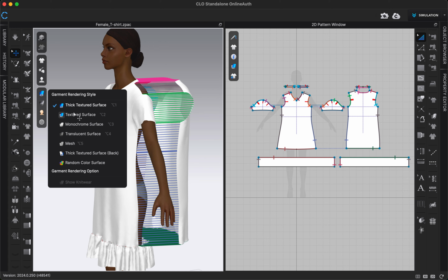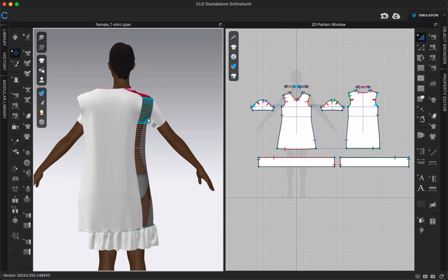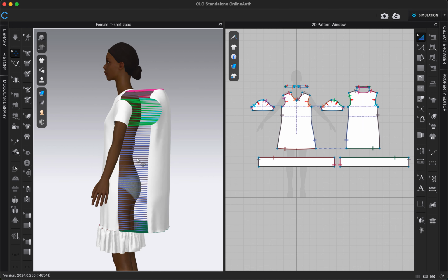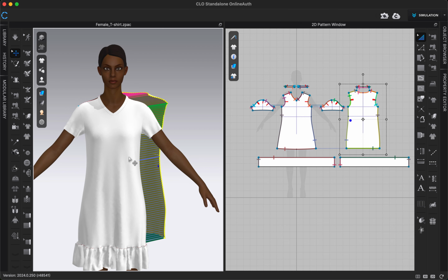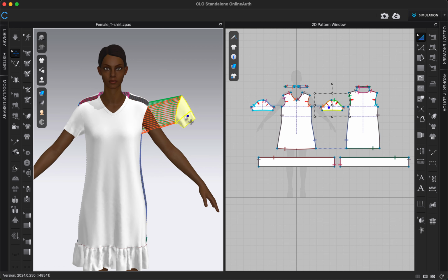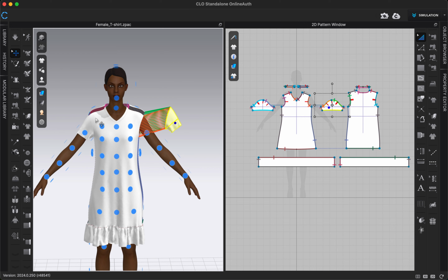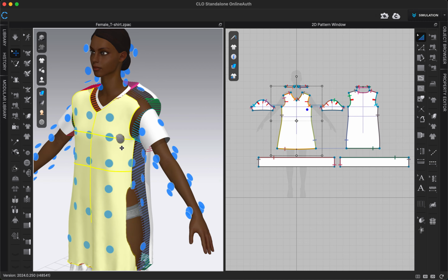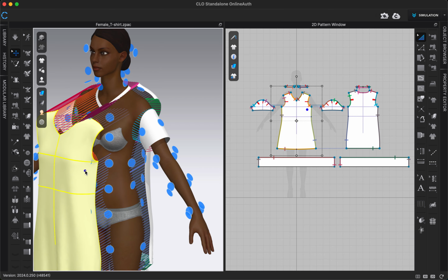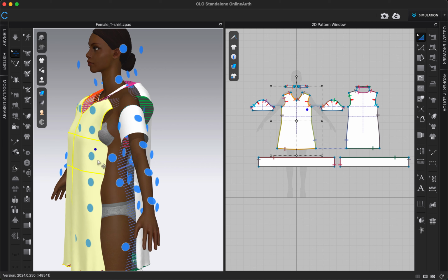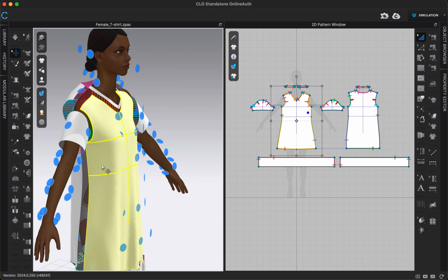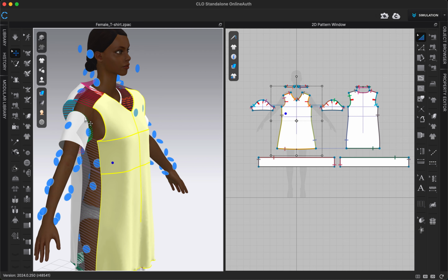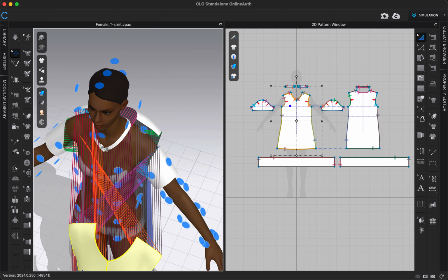And so this could be a way to check if your sewing is incorrect, because maybe when we were arranging our pattern pieces, for example, we accidentally placed our sleeves on the wrong arrangement points. So I'm going to turn on my arrangement points with Shift F and arrange these sleeves on the wrong arms. You can see now that when I'm looking at these threads, the seam lines are not matching up. So the seam line here on this front armhole, the threads are not connecting to this sleeve. And if I pull it far enough out, I can actually see they're crossed.